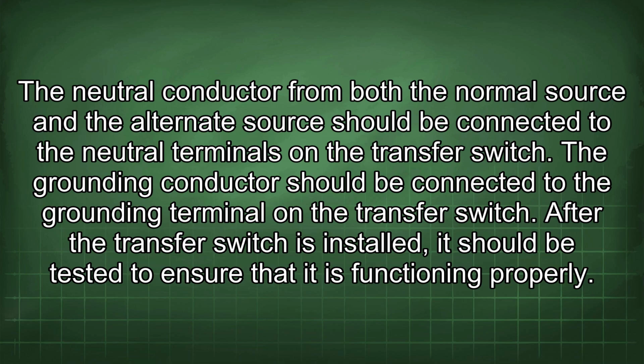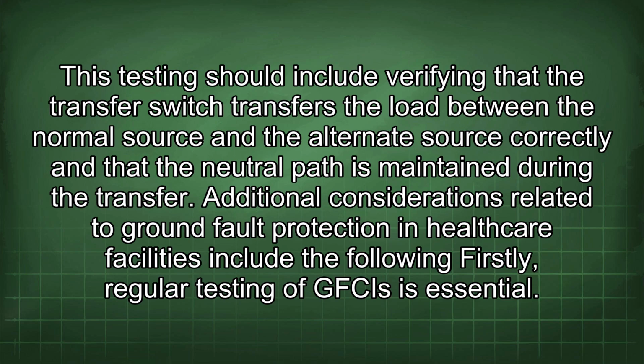After the transfer switch is installed, it should be tested to ensure that it is functioning properly. This testing should include verifying that the transfer switch transfers the load between the normal source and the alternate source correctly and that the neutral path is maintained during the transfer.